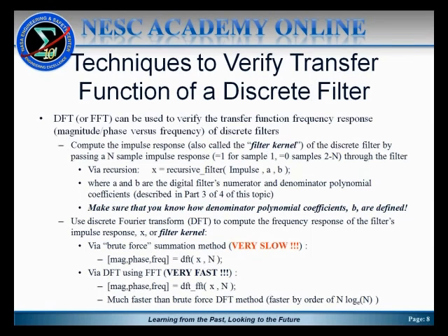As I attempted to provide some guidance in part 3 of this presentation, it's very, very important to make sure you understand what assumptions went into computing the discrete filter coefficients for a digital filter, and particularly the denominator coefficients. There's a couple of conventions that are used there. One is you assume they've been computed such that the denominator has a leading coefficient of 1, which is usually not even provided to you because that's assumed.